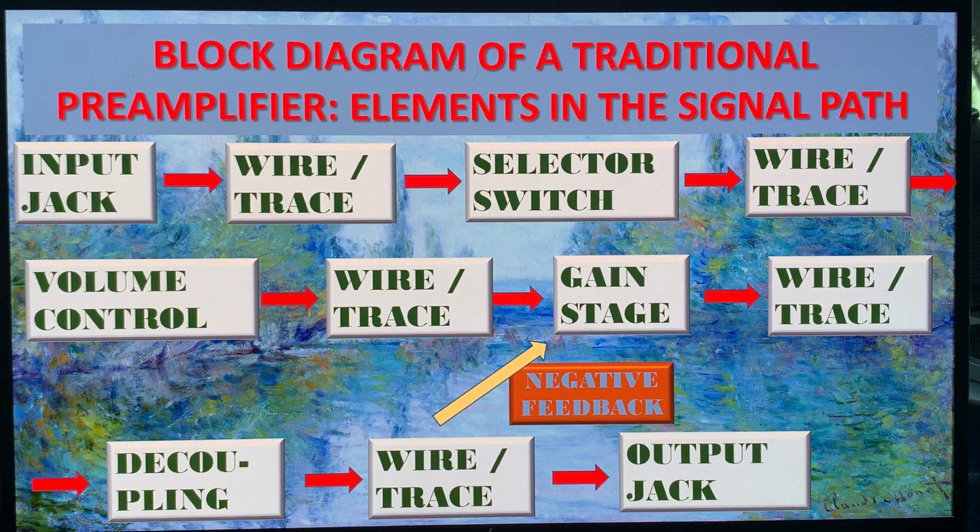Also here I did not show one more thing, that the decoupling stage, it's not just a decoupling capacitor, but there's also a resistor as well that sets the output impedance of the preamplifier.